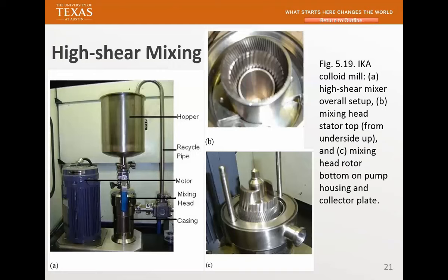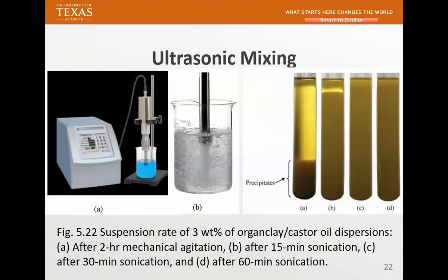This is real high shear mixing. It's almost like what we call a rotor-stator. Basically, you suck your particles in there and grind them, and then you have very, very good high shear mixing. We were able to make a lot of clay nanocomposites from there for films. Okay, so that is also scalable.